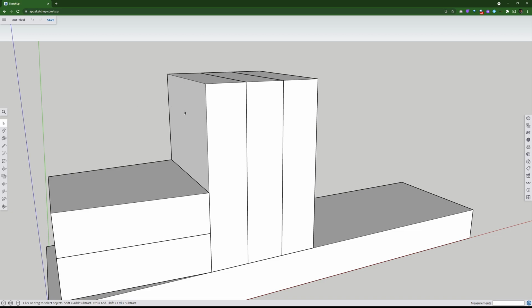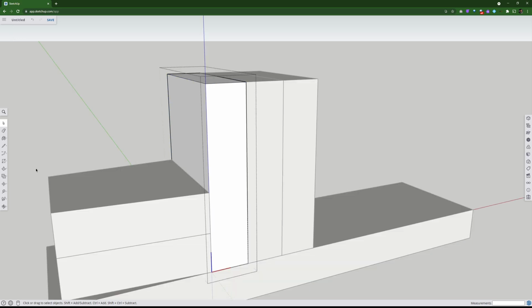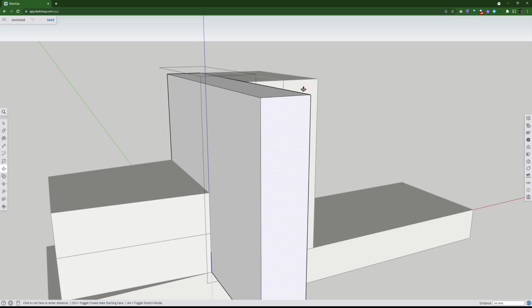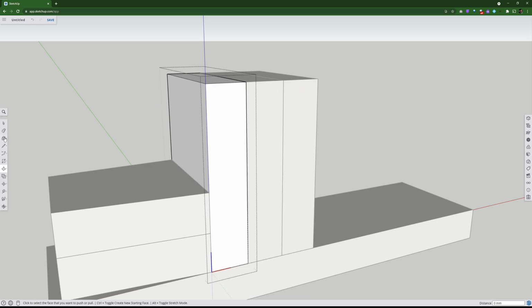Let's fix one problem at a time. I'm going to click on the first part, the front object, the front piece. I'm going to right click and make it a unique piece. It's its own piece now. So when I edit, it shouldn't affect anything else. Escape. Now, to avoid that end going back like this, here we go.